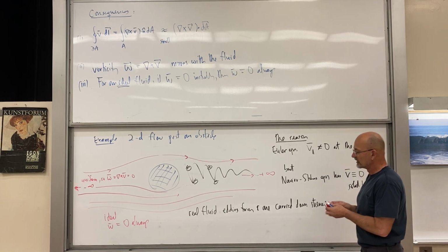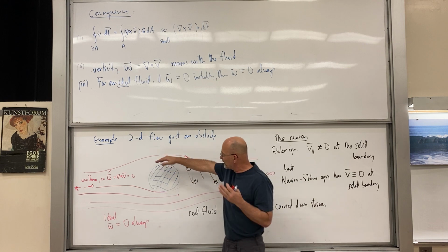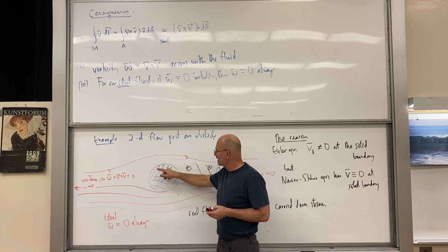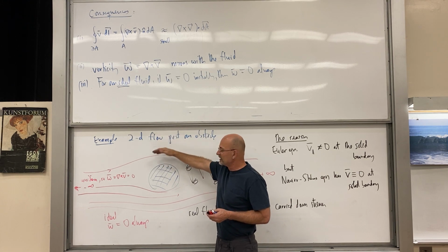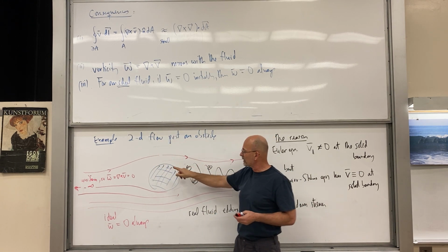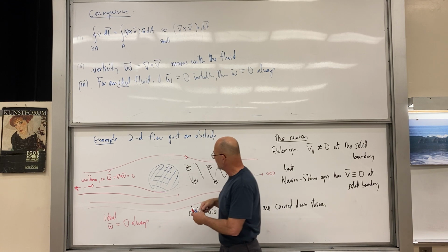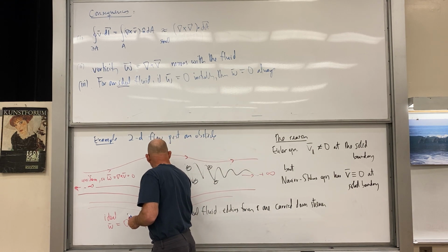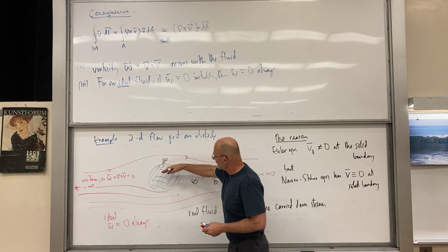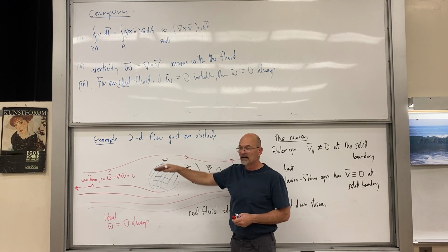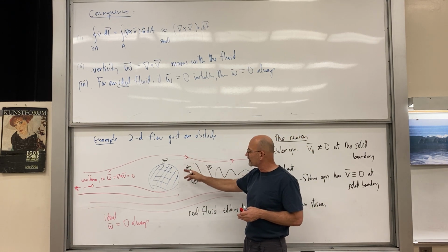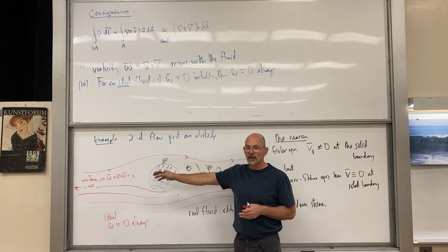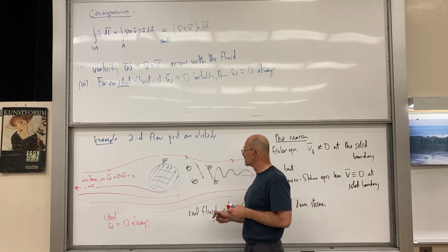Okay, and this can even be illustrated here now. Suppose this is a real surface, a solid boundary, and velocity vanishes here. Then you're going to have a gradient in the x component, right? It's going to go from 0, so the real one here, this picture's going to have a lot going on. There's a 0, right? You're going to have the speeds increasing, and in the other components as well, such that the curl is not going to be equal to 0. We'll actually calculate those later.